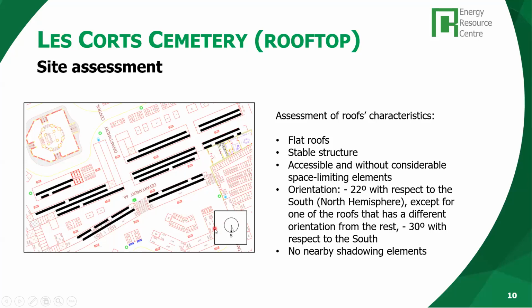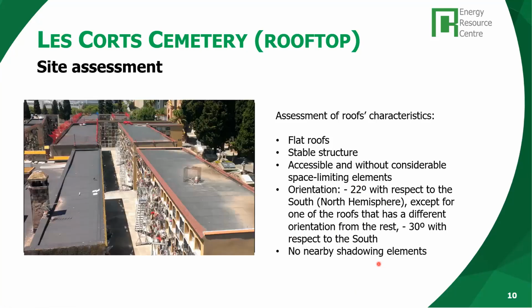Okay, so being Barcelona in the northern hemisphere, of course, that's convenient for an orientation looking at the southeast in this case. Well placed in that sense. The orientation is minus 22 degrees, slightly towards the east with respect to the pure south, and no nearby shadowing elements. That is important.